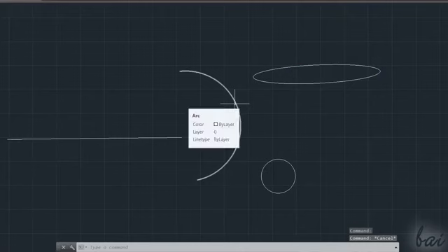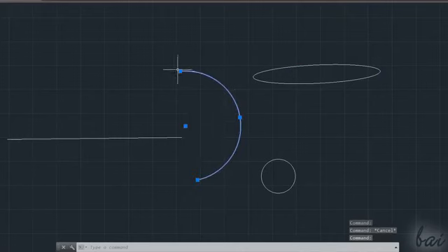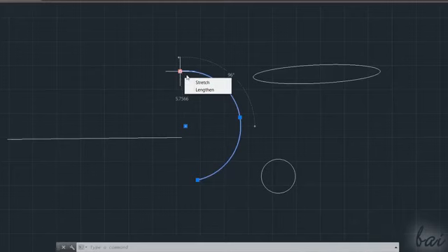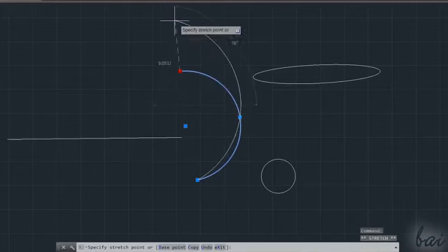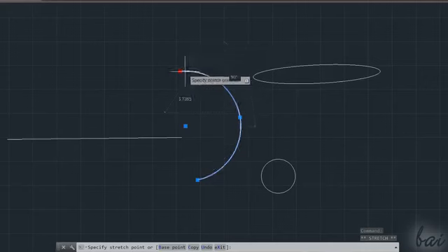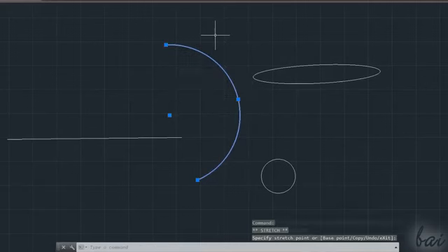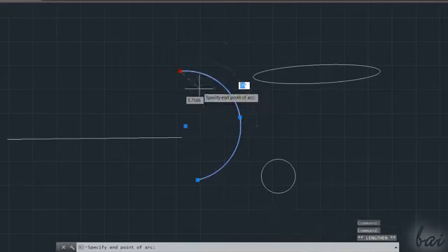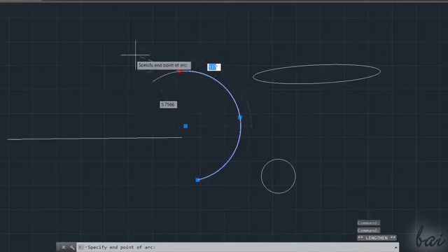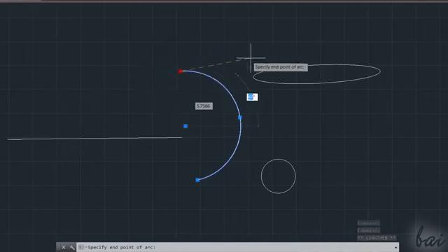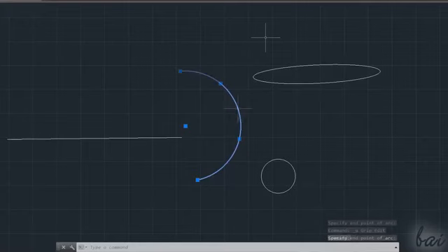On lines and arcs, you also get a dialog box if you hover on a node for some time. Use Stretch to move the endpoint chosen independently in order to change the object shape. Use Lengthen to stretch the line length or the arc length without changing the basic object shape. Use Radius to adjust the arc radius.